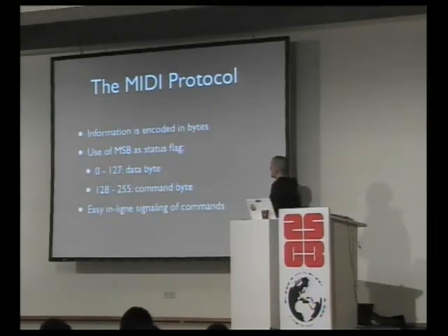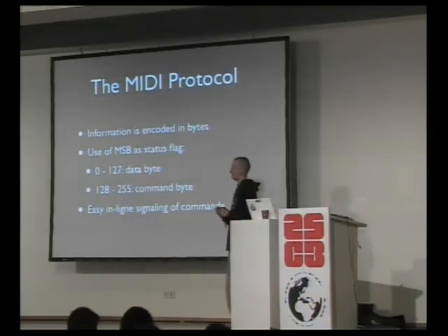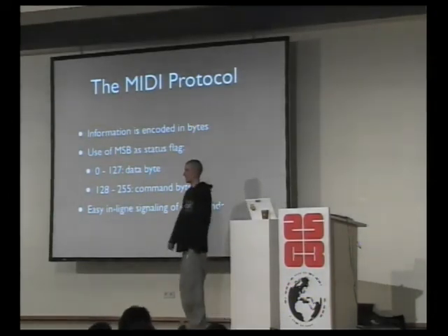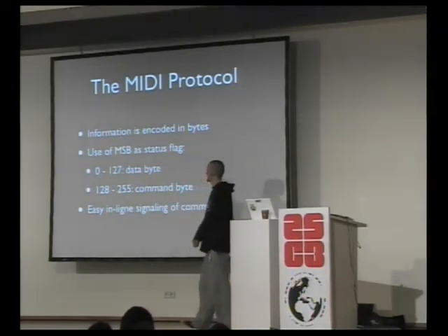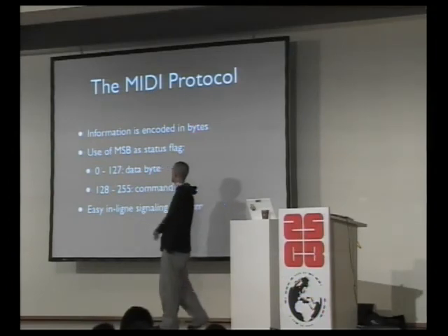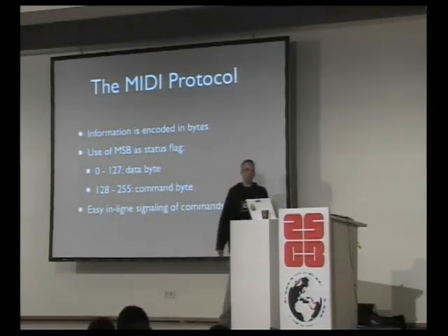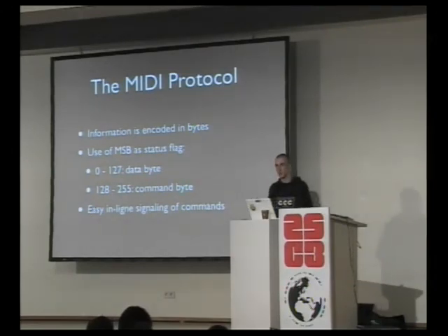So the MIDI information on the cable is encoded in bytes, but there's one slight trick: the most significant bit of that byte is used as a command flag, so you can do signaling of commands. All the values from 0 to 127 are data bytes, and the rest are command bytes. So it's pretty easy to check if you just received a command or a data byte.